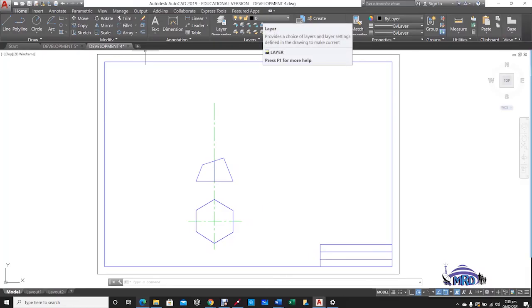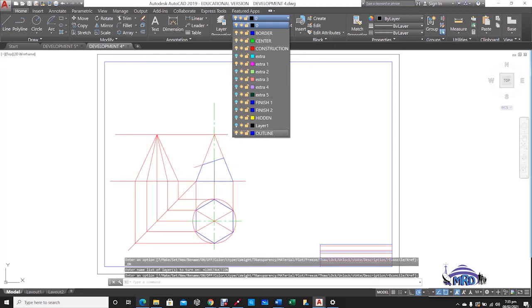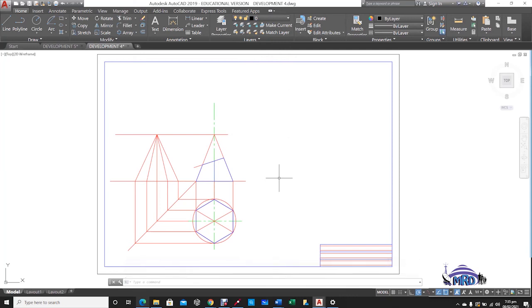Now, we have represented a frustum of a hexagonal pyramid, and if we drop in the construction lines for you to see, we've gone through that process on the previous drawing, so I'm not going to spend a lot of time with that, but we need to produce the end view. The construction lines represented here are pulling the view over to the side so that you get the end view in position.